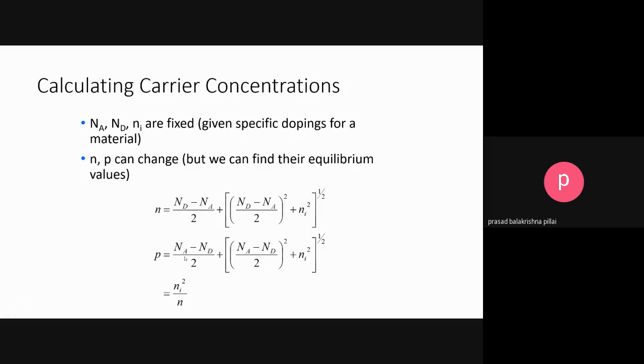So in most of the standard textbooks, for an extrinsic semiconductor, the electron concentration is taken to be equal to the donor density, and in the case of a p-type material, it is taken to be equal to the acceptor concentration. So this is a very important relation. Strictly speaking, it is not true, because at thermal equilibrium the intrinsic carrier concentration is also there.